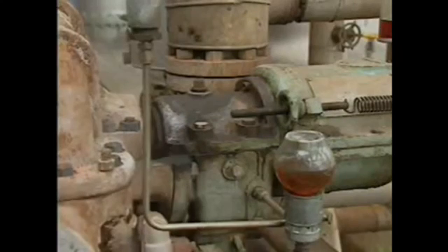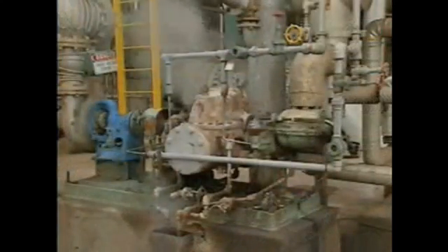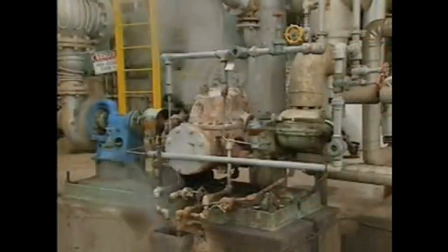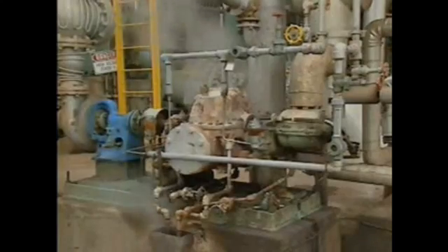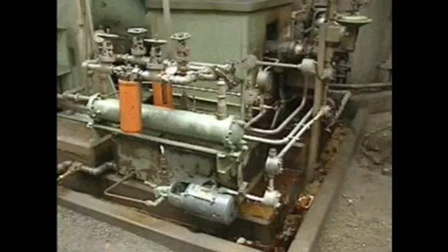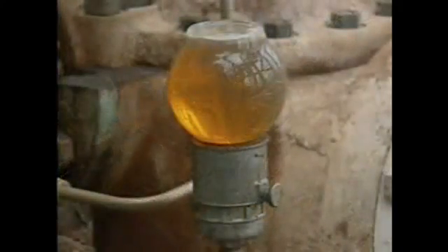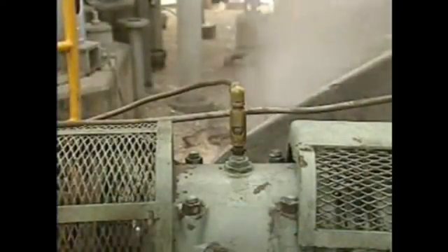We'll begin with lubrication methods that use oil. Generally, oil is used to lubricate bearings installed in machines that operate at a high speed under a light load. There are several different ways to provide oil to rolling contact bearings, including forced circulation, constant level oilers, oil baths, splash feed methods, and drip feed methods.